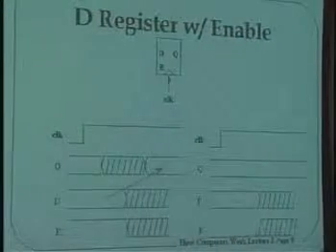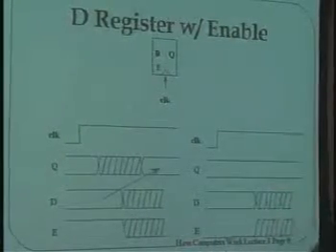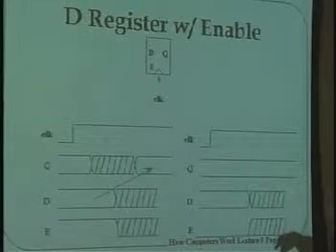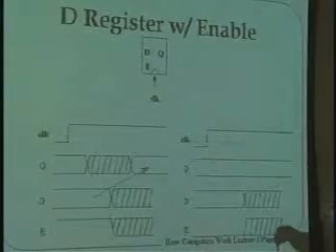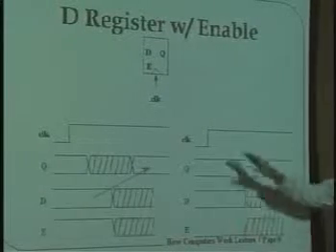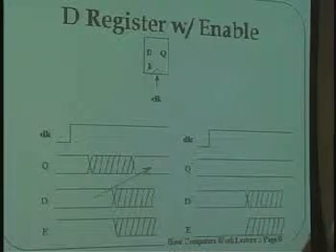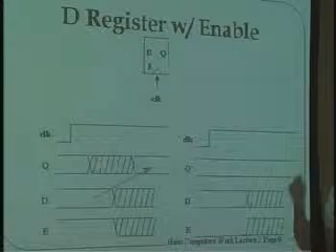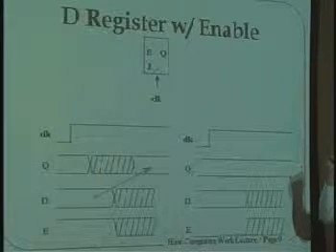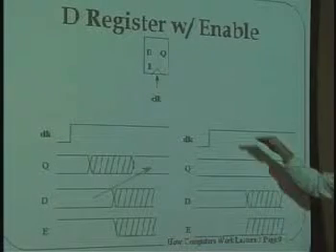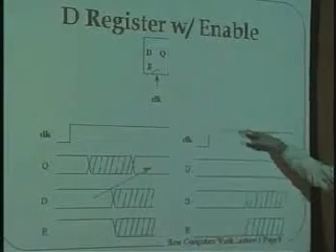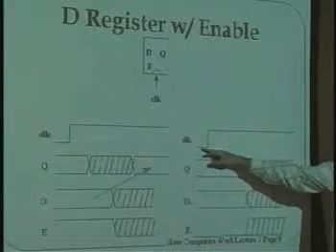Q will have that value from the time you take the picture until you take the next one. So here's a timing diagram, and this is the first time you're actually seeing waveforms that look like this. Because we're taking this course starting with software and instruction sets and going down to physics, you don't need to worry about whether this is a voltage or a current or a pressure of some fluid, except to understand that things are digital in this course, where this high value right here might be a 1, and this low value over here might be a 0.